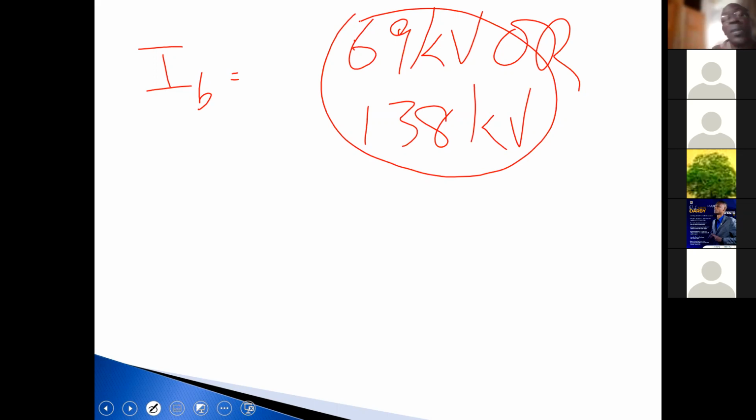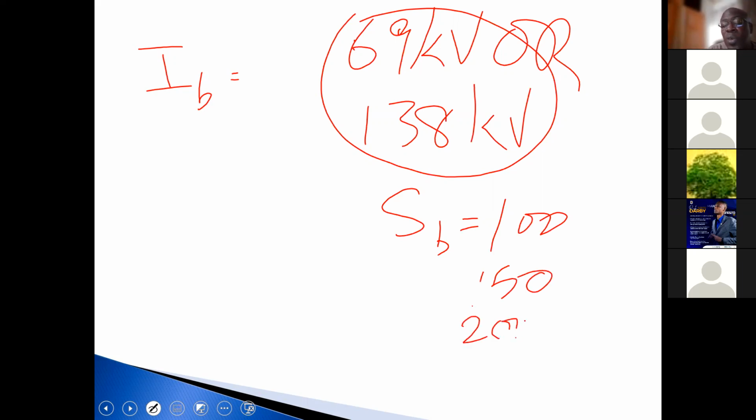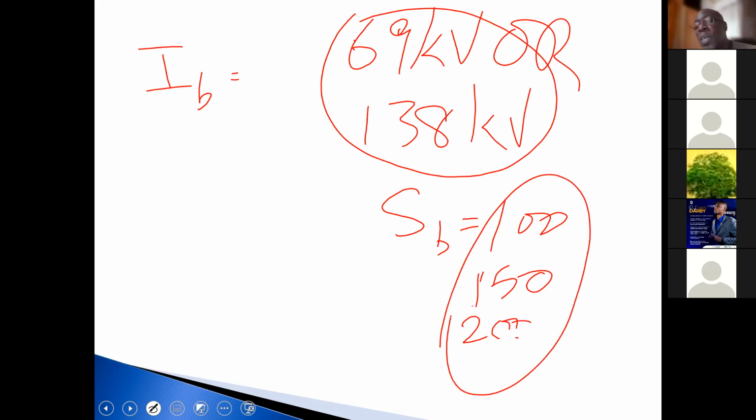All right. So what would be the S base? What's S base? Come on, man. You only have 10 minutes left, you know. What would be S base? 100 MVA, sir. 100. All right, anything. 100, 150, 200. You go and choose it, right? Fair enough? Because it's arbitrarily chosen. Of course, you're not going to choose 10 because that is much too small, no?